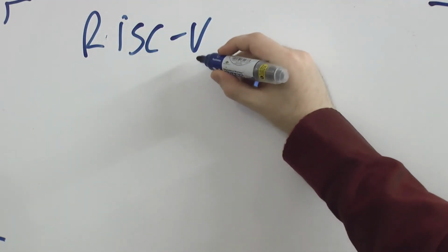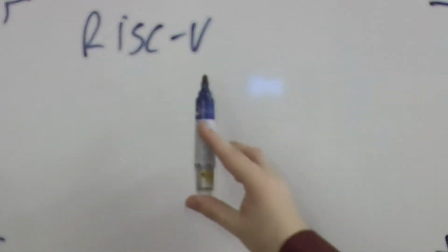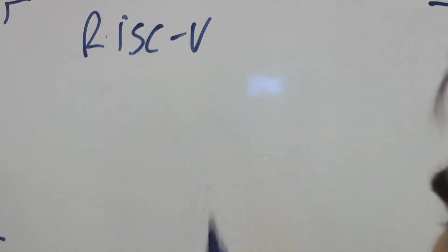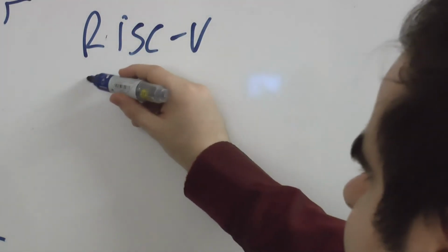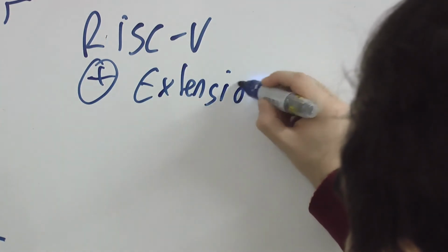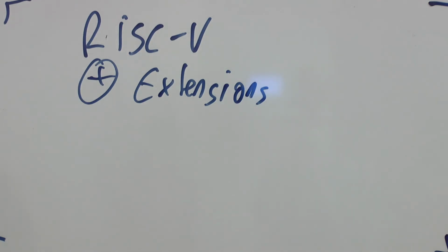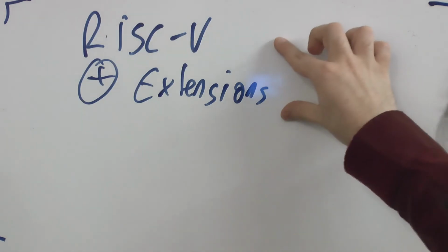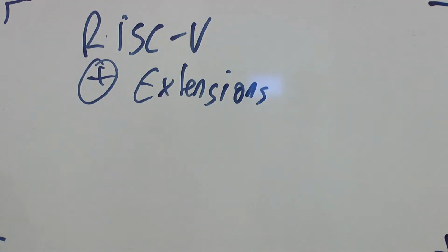Now, when it comes to RISC-V, the RISC-V is an instruction set. So it essentially describes assembler language and how a controller has to behave. And in addition to that, there are also extensions, which can, but don't have to be implemented. And so even just in the official specification, the vendor already has the ability to create different types of cores.